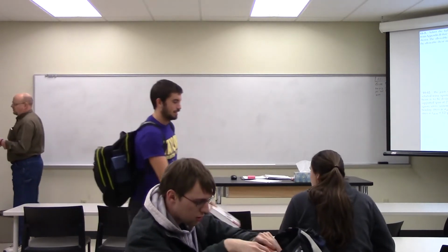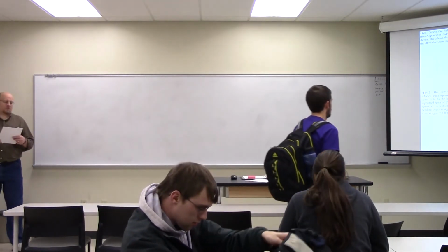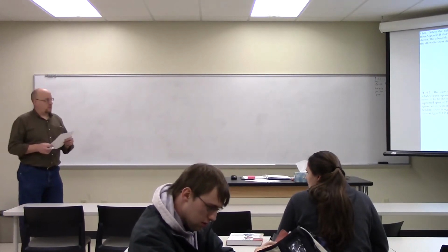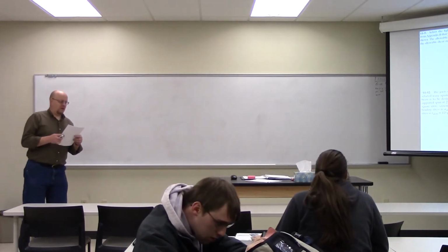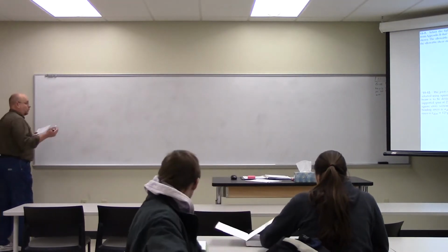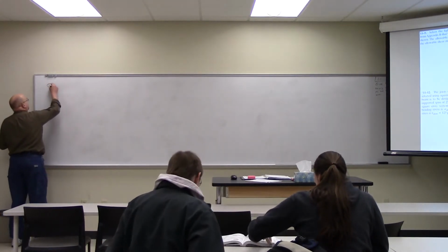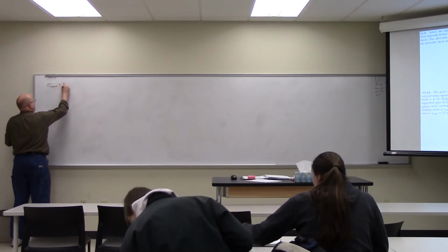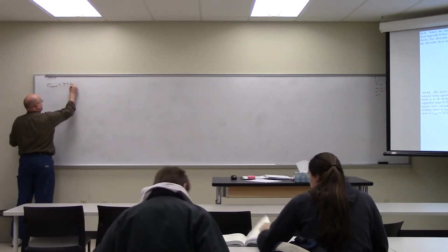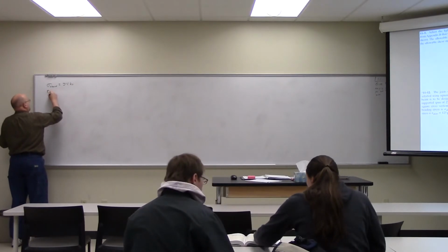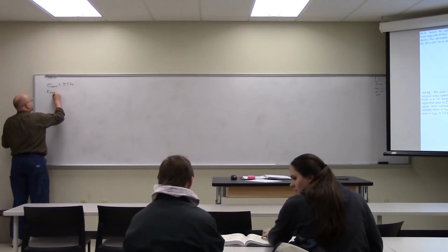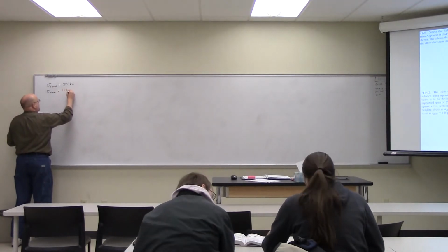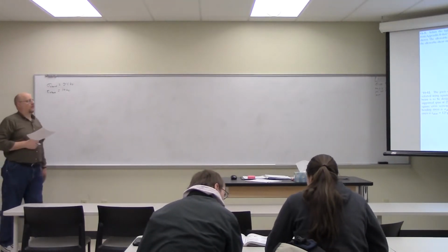Select the lightest weight steel wide flange beam from Appendix B that will safely support the machine loading shown. So we have this picture. The allowable bending stress, or the allowable normal stress, should have said, is 24 KSI, and the allowable shear stress is 14 KSI. And there's the beam.